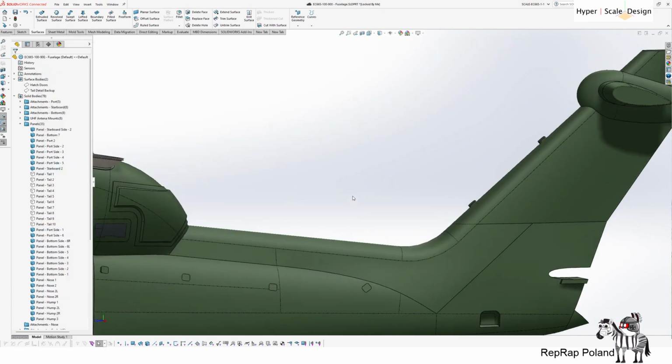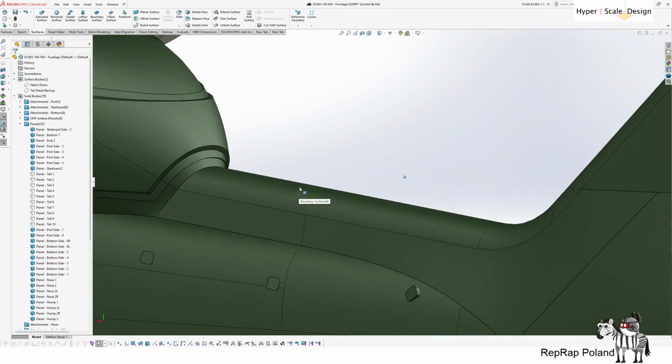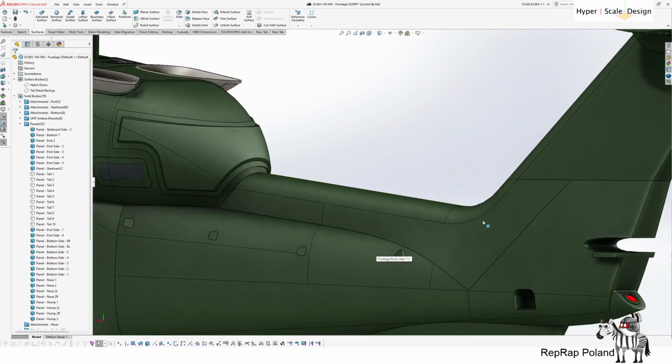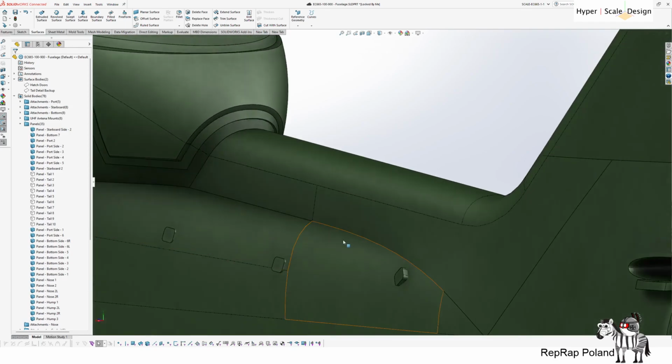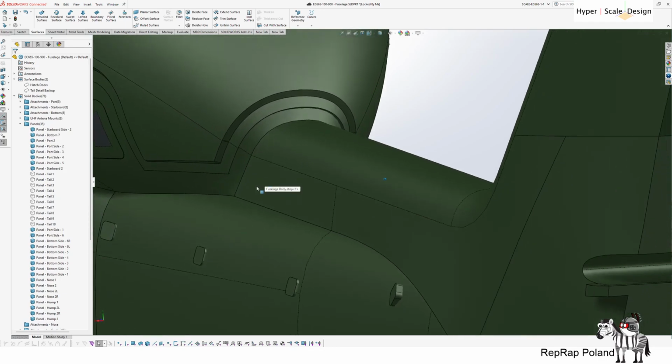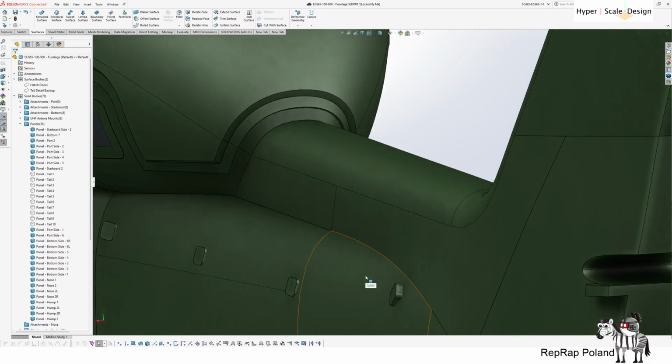So if I look at the geometry, this means we're going to be creating a panel going along the top section of the tail. But we want to have it overlap here, with a fixed width of also 24 millimeters. Now what is really tricky here is, if you look, it will be going along multiple faces that have been lofted, but as well along this crease.